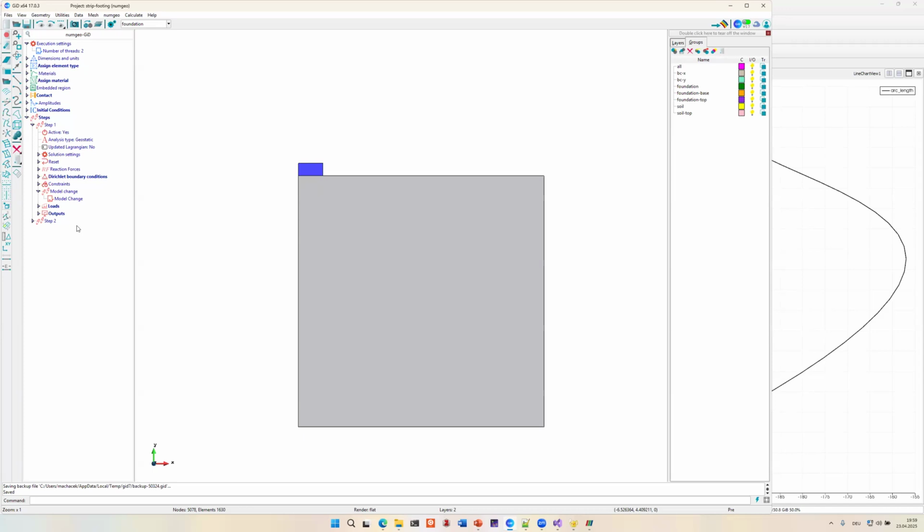But at the time, with the current interface that you have here, you would increase the gravity and decrease the gravity. And if you want to excavate a material, you would just decrease the gravity and change the material to, let's say, an elastic material with a very, very low stiffness. So this is actually also what is done inside the commercial programs, just that they do it for you. But currently you have to do it, let's say, by hand. But we are working on having, let's say, easier access to these two types of processes. Yeah.